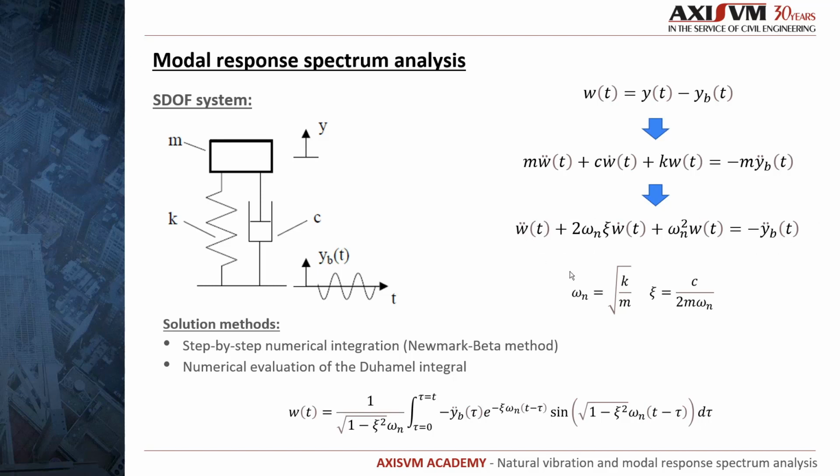Here we have again the angular natural frequency, and we introduce also damping in the system with the velocity proportional c constant. In the last equation, we see the ξ parameter, which is often used and describes the damping ratio of the structure. In the case of seismic design applications, the base excitation time history corresponds to the measured or artificially generated accelerogram. All we have to do is solve the differential equation and we obtain the displacements, velocities, accelerations, and therefore the inertial, damping and spring forces of the system.